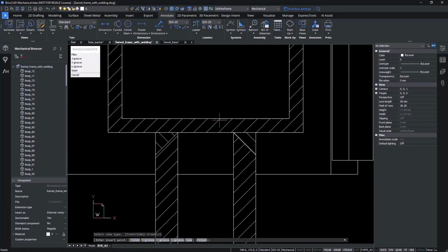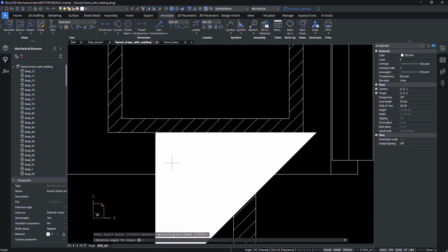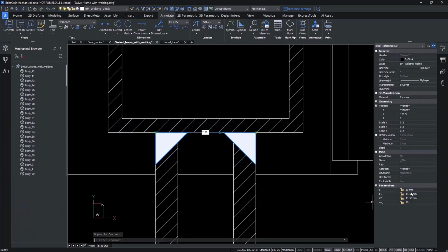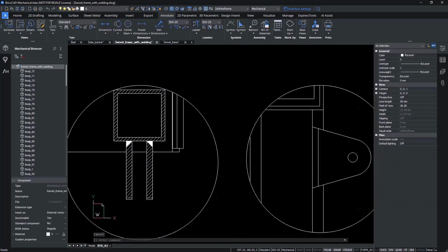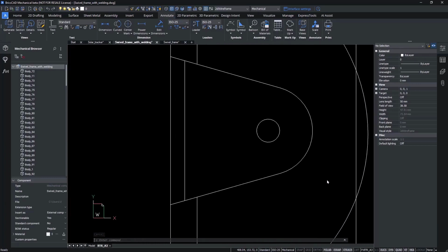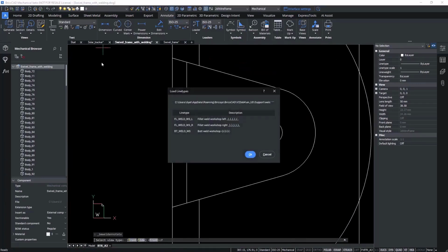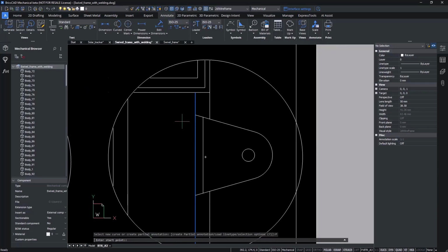The side view annotation process is the same for groove and fillet welds. The top view annotation process is only slightly different. Here, you'll need to specify the beginning and end points for the weld bead orientation, or the caterpillar. You may need to use the flip tool to position the bead graphic properly on the part.